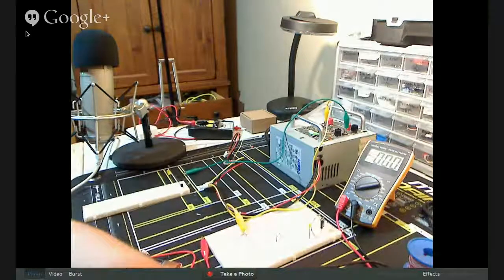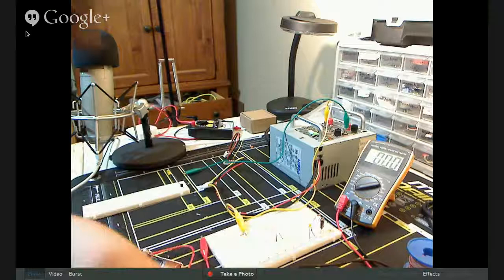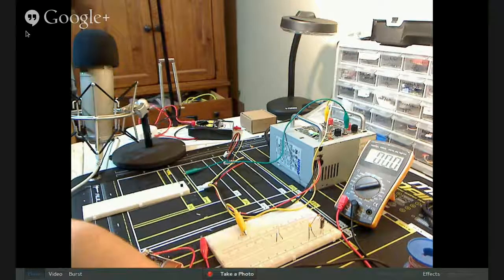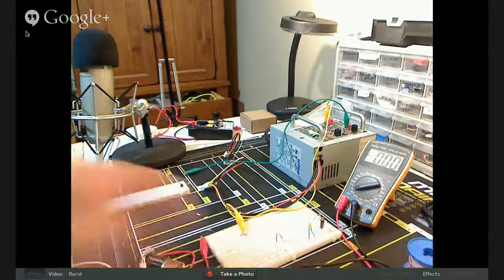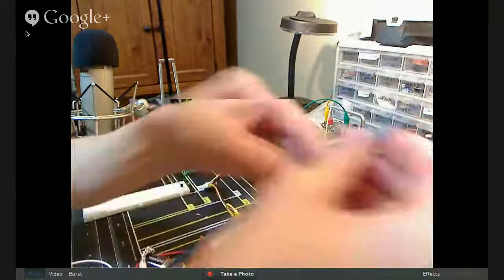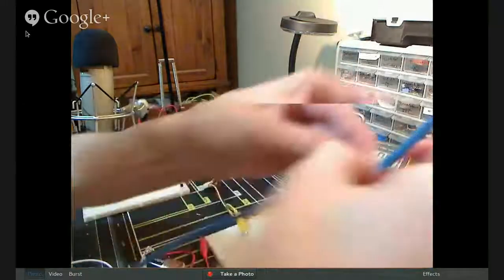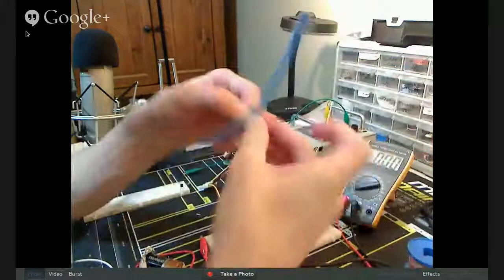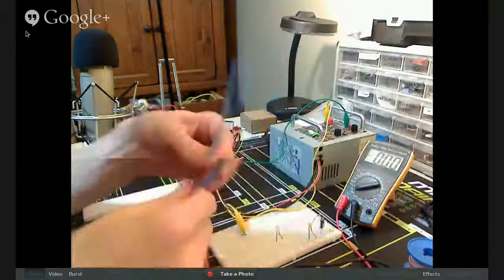Or if you have wire strippers, you'd be able to get this off too. You just need to be careful either way. You might slice your finger open, or the other way you might slice into the wire underneath. Just very carefully score down, and you'll be able to open it up and reveal the wire inside.